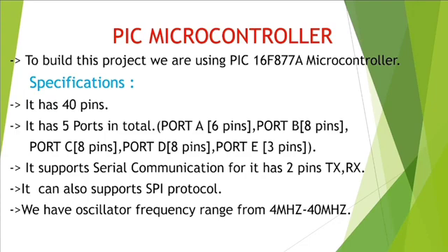It supports serial communication through its 2 pins TX and RX, that is transmitter and receiver. It can support SPI protocol, Serial Peripheral Interface Protocol. It has oscillation frequency range from 4 MHz to 40 MHz. Clock frequency range of 4 MHz to 40 MHz.